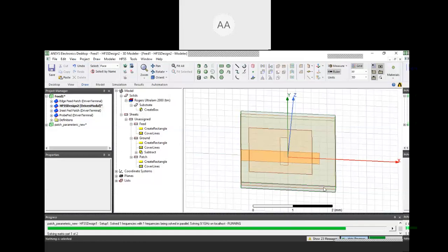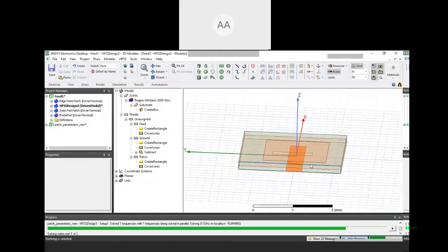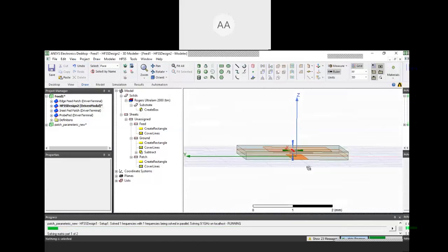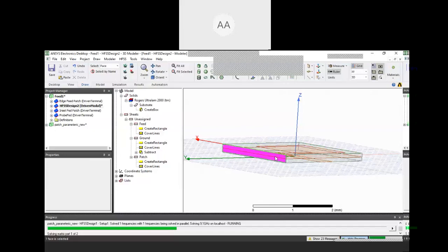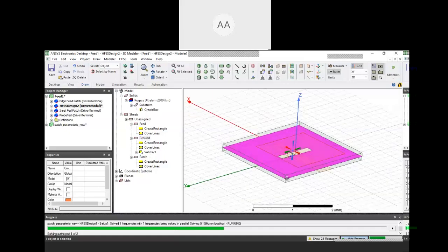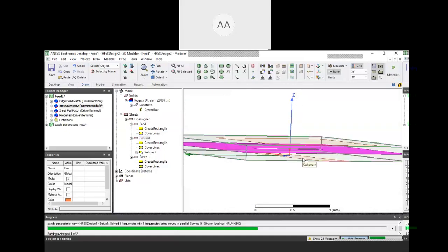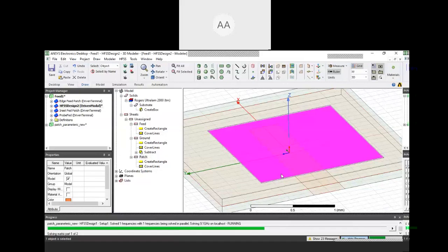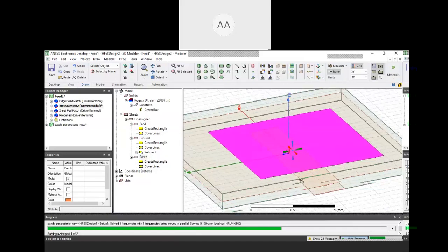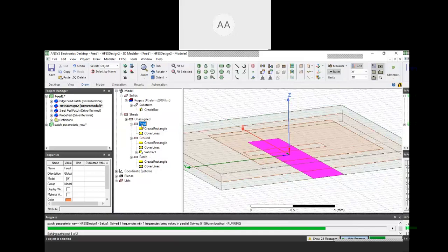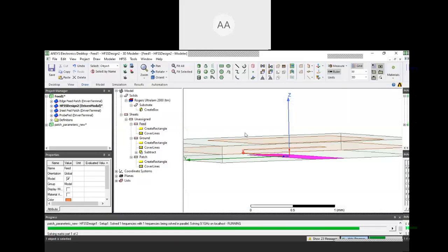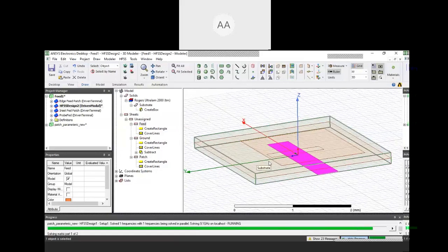And there is one more that is called proximity coupling. In proximity coupling, we just reverse this. This is aperture coupled: on the top is the patch, in the ground we have the slot, and below the ground we have the feed line. Patch, ground, and the feed line at the bottom. And there is something called proximity coupled also.